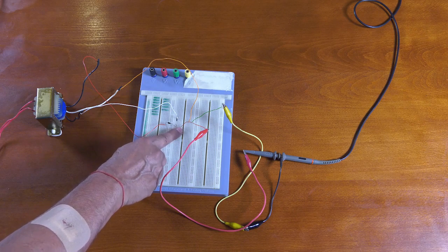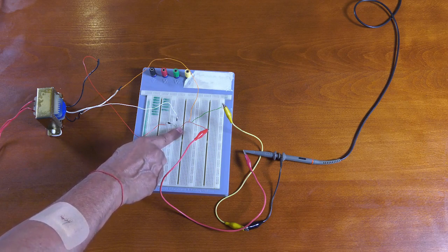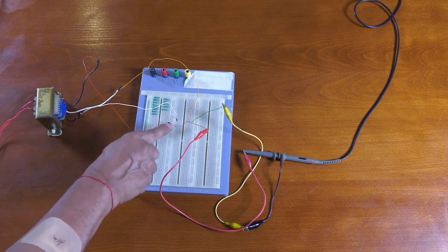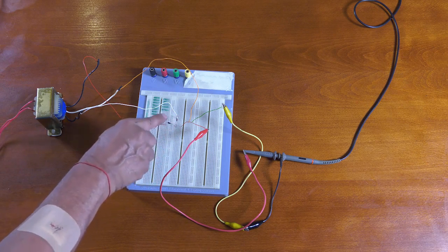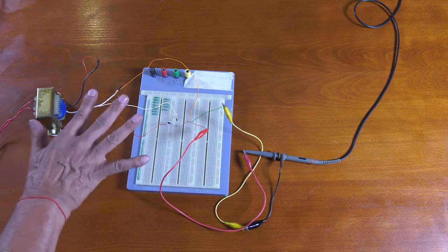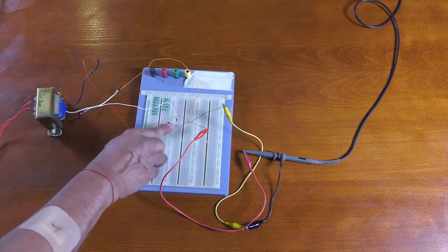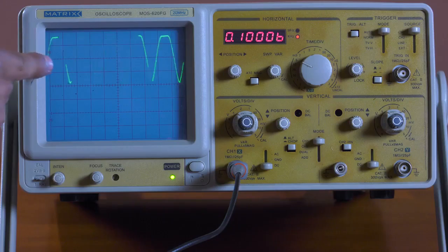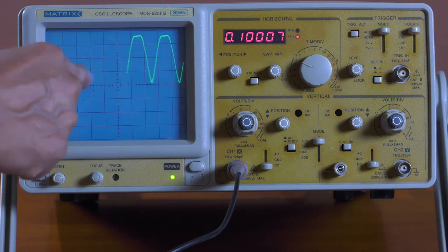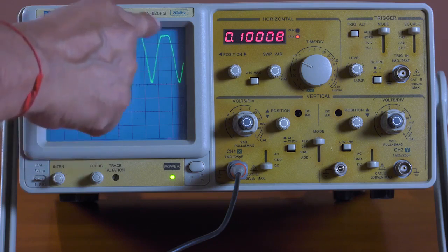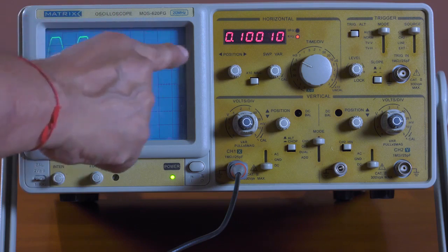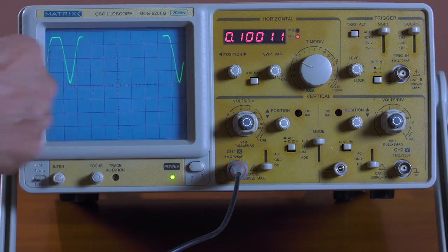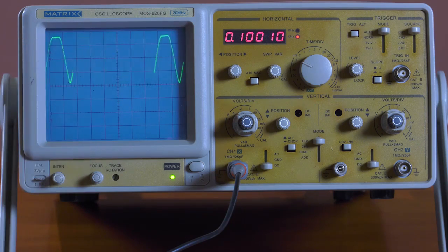And notice what happens to the waveform now. Also take particular notice as to what happens to the frequency when we are using a full wave circuit like we are seeing now. So this circuit represents rectification. The type is full wave using a center tap transformer. This is the waveform that is represented by a full wave rectifier that is using 2 diodes, and as we have explained before, we are using a center tap transformer. You could use a standard transformer and you'll get exactly the same waveform.